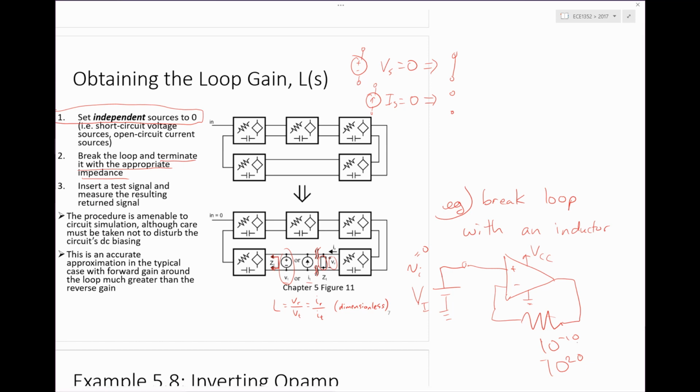And as you probably know, all SPICE simulators do those two simulations totally separately, basically just like you're taught in undergrad. First, the simulator does the operating point analysis, figures out what all the DC voltages are, and then if you do an AC analysis, it linearizes everything first, and then runs the AC analysis, which is why it's so fast, because it's just a linear circuit, a linear problem at that point.